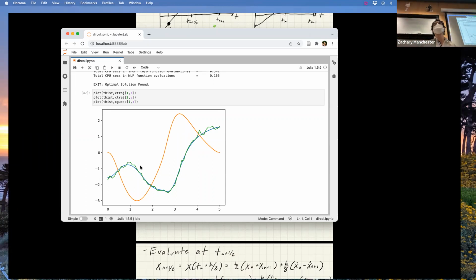If you start from an infeasible start and then you stop before convergence, what do you get? Yeah, so that's the counter to what I was just saying. With DDP, if you stop early before it converges, you still have something reasonable that you can maybe execute, even if it's suboptimal. Here, if you stop early, it doesn't necessarily obey the dynamics constraints. It only obeys the dynamics constraints at convergence. So if you stop early, you might have something that's completely unphysical garbage that is not able to run on the robot, which is bad.